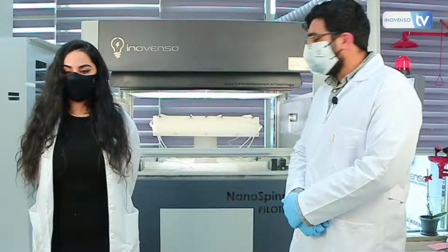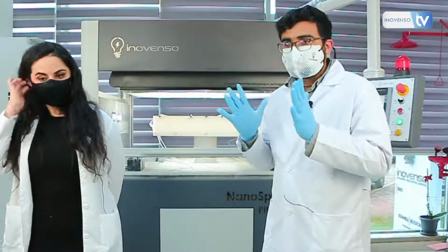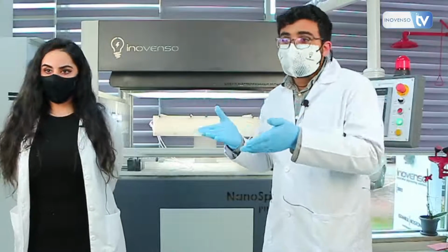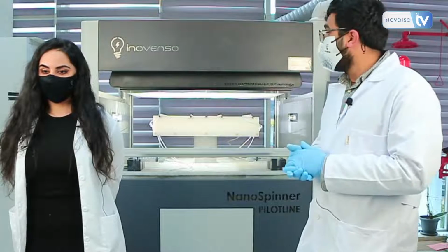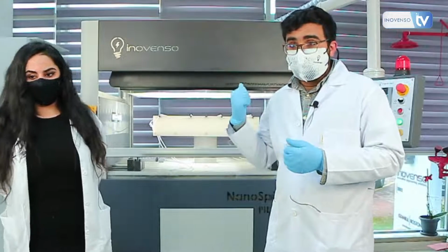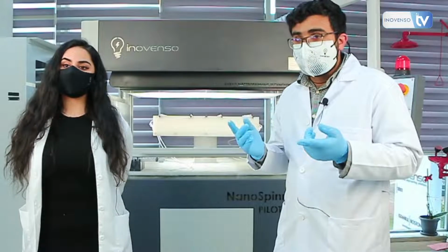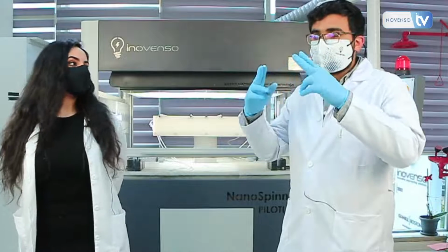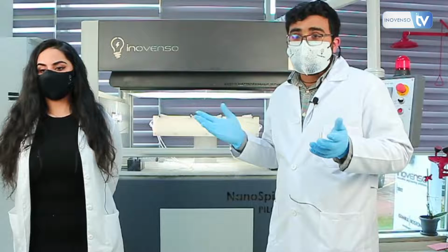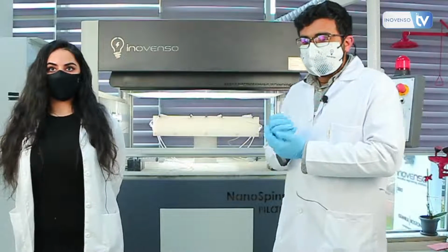So when you say multi-needles, they have their own electric field, and this causes the jets to have some sort of repulsion. In different machine systems, you would be faced with some sort of issue. But the benefit of our machine, the hybrid electrospinning, the nozzles, and the homogenization system that we've incorporated in this machine, is that the machine is successfully able to eliminate this repulsion or interaction between different jet streams and the clogging issues. So we don't have that issue when we incorporate homogenization.